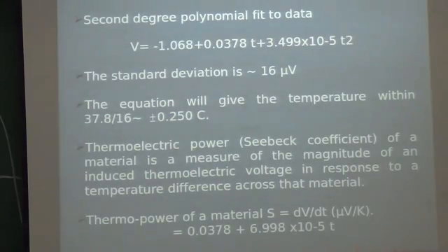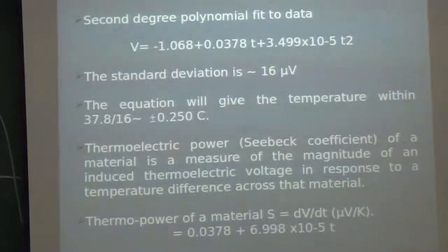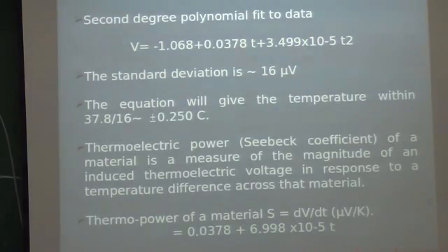That means in the case of silicon diode, we got an accuracy of 0.5 degree centigrade, but here we are getting 0.25. We can also find out the thermoelectric power. If you differentiate this, V is equal to, so it is dB over dT. So dB over dT gives us this. So this gives us a thermoelectric power of 40 microvolts per degree. We discussed the copper constantan thermocouple. So this experiment will give us a feeling that we can make use of a copper constantan thermocouple and a forward bias diode, by allowing some current to pass through, as a temperature sensor.